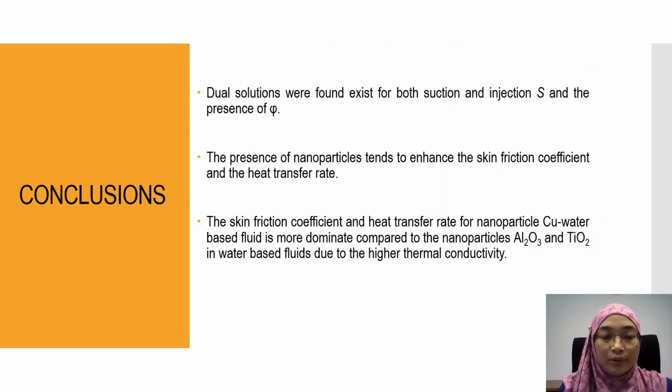There are three main conclusions in the study. The first one is that dual solutions were found to exist for both suction and injection S and the presence of nanoparticle volume fraction. The second is that the presence of nanoparticles tends to enhance the skin friction coefficient and the heat transfer rate. And the last one is that the skin friction coefficient and heat transfer rate for copper nanoparticles in water-based fluid are more dominant compared to alumina and titania nanoparticles in water-based fluids due to the higher thermal conductivity.